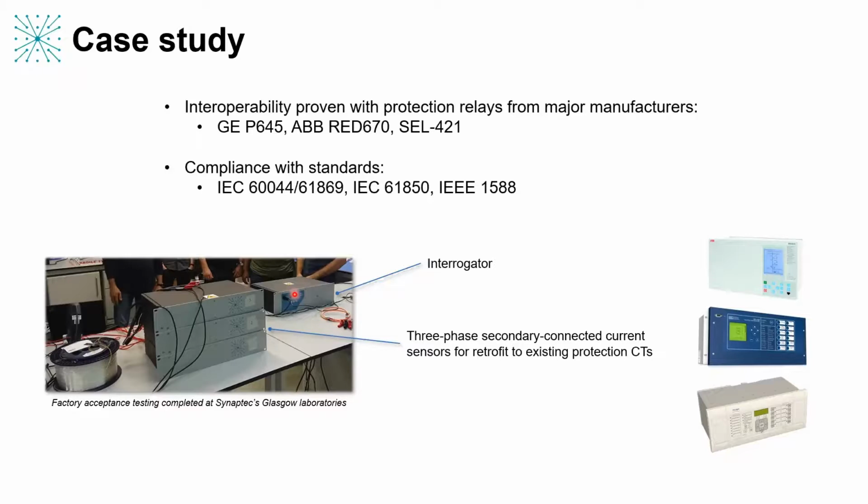Yep, of course. Well, the main one I would say is using a dry contact to perform the trip, just like a traditional protection relay would. So that's very easy for us to perform, and that's available as standard. We've also been asked for various different digital outputs, and we're very flexible about that. Our in-house software team is very capable of either switching between different supported formats, or even supporting new formats if we don't currently do so. So we can be very flexible in that regard.